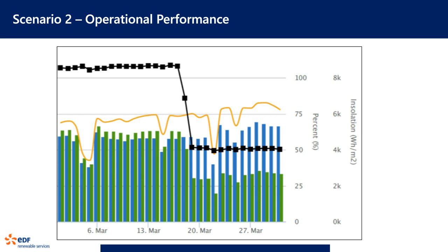Well, the first step is to understand precisely what the problem was. In this case, it was a leaky bushing on a transformer that caused it to fail. There's a couple of questions asked right off the bat. The first one was, is this item covered under warranty? If so, do we have guarantees for response time from the OEM to get on site and make the repair? In this case, it wasn't covered as a warranty item, so then we look at parts availability: are those parts in a spare inventory, when can we schedule someone on site, and how can we make the repairs?